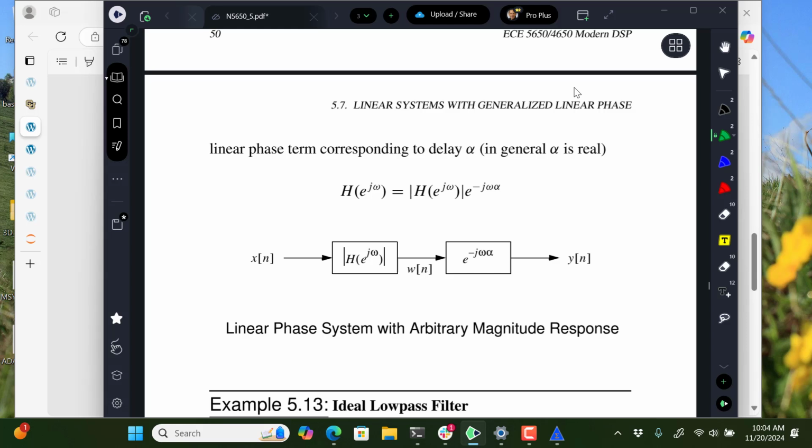And what this picture is showing is I'll take any magnitude response that I find useful, flat in the pass band, good stop band attenuation, and I want the response of my filter to have that magnitude response. And then I just want the phase to be this nice linear phase, because I know if I take minus the derivative of that phase, I'll have constant group delay in the band. Just tell me how to make filters like that. And that's what this section is about.